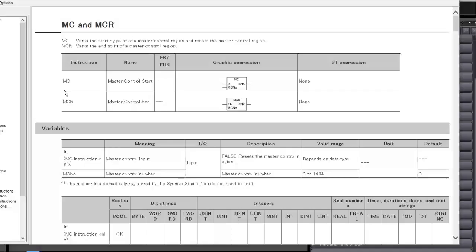It would also stop any motors that are running. So basically, it brings everything to a screaming halt. Now, that's a master control relay. That could be programmed in. Before PLCs, it was actually hardwired in and would shut the power off to massive amounts of relays and equipment.